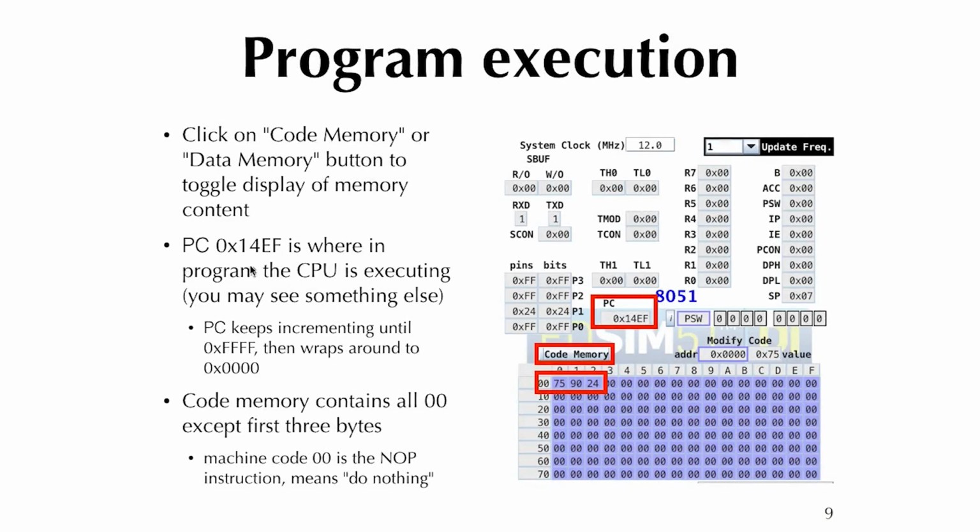So that's where it is, and it just keeps running. And with 8051, the instructions are not fixed width. In other words, some may be single byte instruction, others might be 2, 3, how many bytes. So the PC gets incremented by the size of the instruction. So sometimes it increments by 1 byte, sometimes by 2 bytes, sometimes by 3, depending on how many bytes that particular instruction is. Unlike, as you may learn, RISC architecture, everything is fixed, 4 bytes instruction or something, right? But even RISC have been trying to find ways to compress. Now, advantage with variable length is that the code density tends to be higher, so that your program size can be made very compact.